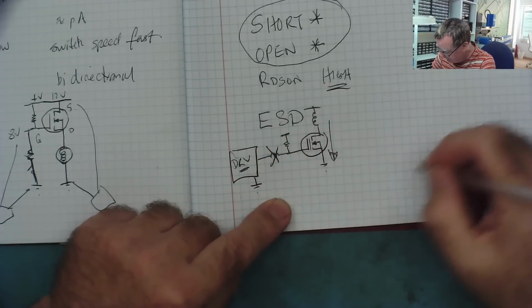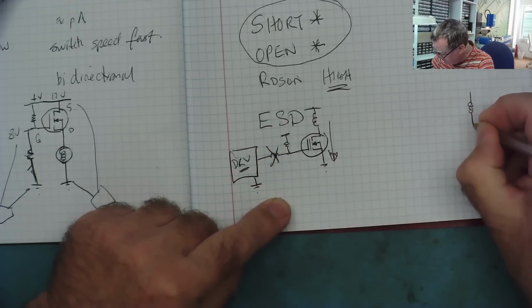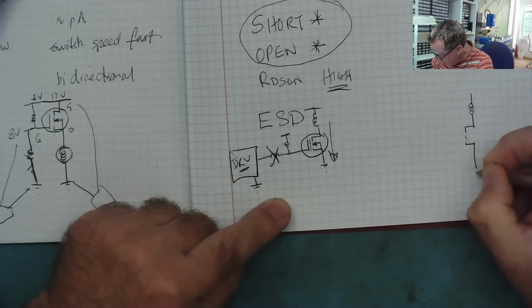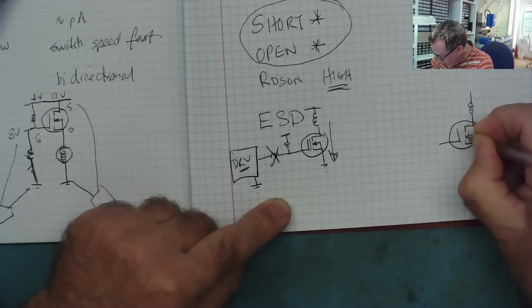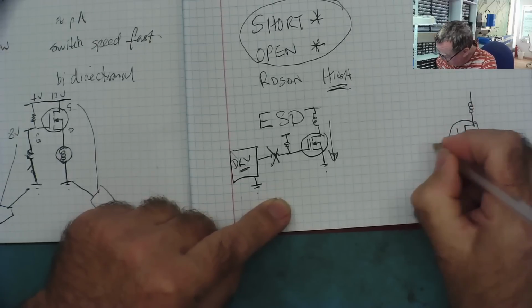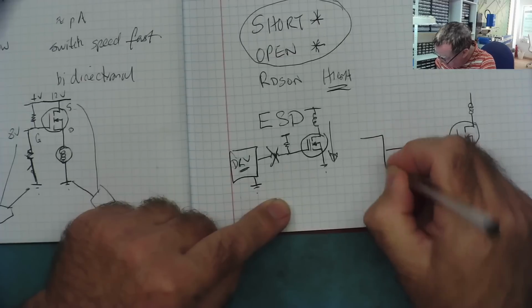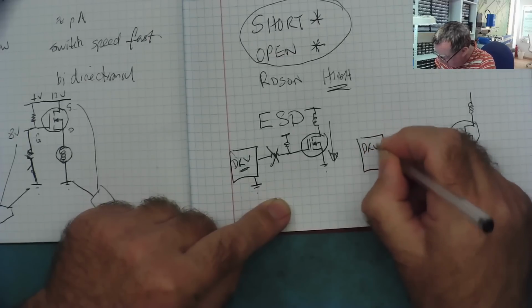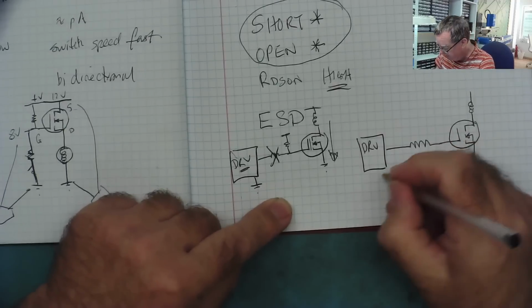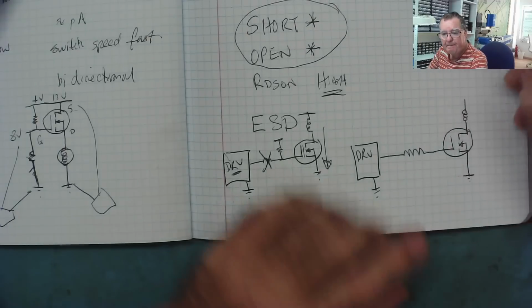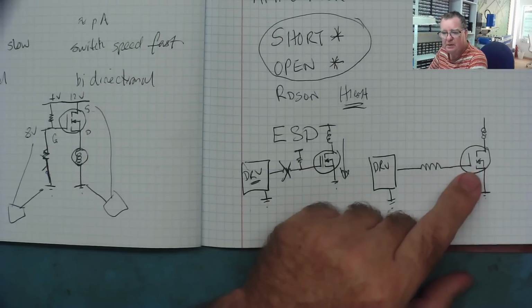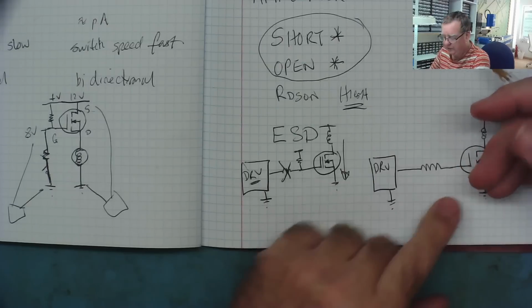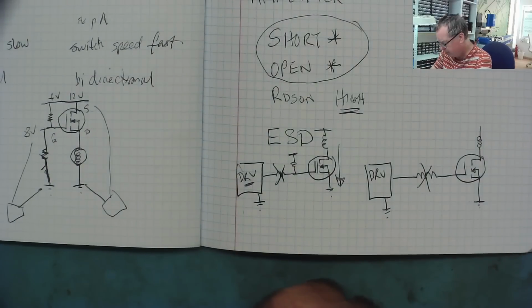Okay, but even if you don't have this resistor, we'll put something back in again, so you've got a circuit like so, no pull-up resistor, just a gate resistor going to whatever is driving it, the driver IC, pulse width modulator, whatever, and then internally that goes to ground. Same thing happens. The MOSFET was short, so you've changed the MOSFET, you found the short circuit MOSFET, you haven't realised this is open circuit.